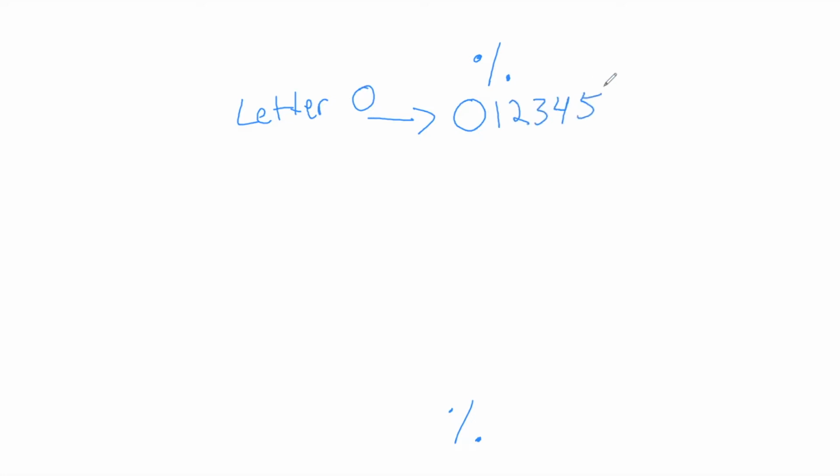All right, this will determine where the program lands in the program list in the controller, and you'll be able to search for it in the program list. You can pull up the program number, but this is how it's going to fall into the controller. And it begins with the letter O, not 0.